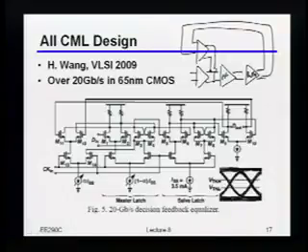There are some additional tricks they played with like bias currents and things like that. Don't worry too much about it. Really the key point here is that if you're pushing on the edge of the speed limit of the technology, then simply replacing the comparator itself with something that has lower swing at the output, just to reduce the number of tau of resettling, could actually be a beneficial thing to do. In this particular case, from a practical standpoint, the common modes also tend to work out relatively nicely, because now I have a CML stage driving another CML stage in terms of the current switching. These are the current switches right here. So from a common mode standpoint, I don't have to worry too much about pulling those things out of saturation and things like that.